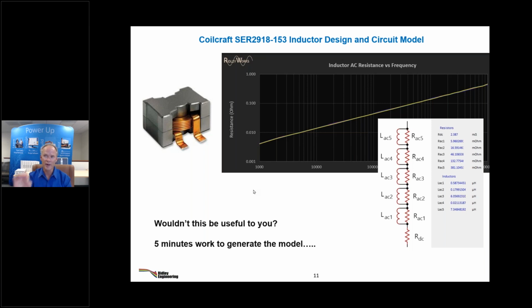So primary, secondary, except that when you split the windings to halve the leakage and cut down the proximity, you increase the capacitance, okay? If you've got lots and lots of windings, having 10 primaries interleaved with 10 secondaries, it's wonderful for proximity, but you might have a couple of nanofarads of capacitance from primary to secondary, and then your EMI is impossible to solve.